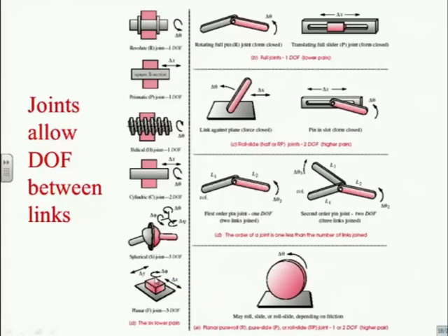I show some other sketches on the left panel here. A screw thread in a nut is a 1 degree of freedom joint. The input is delta theta. I turn the screw. It advances in one direction. So I have one output for one input. That's a full joint. A cylindric joint, this is a round pin in a hole, cross-section thereof.